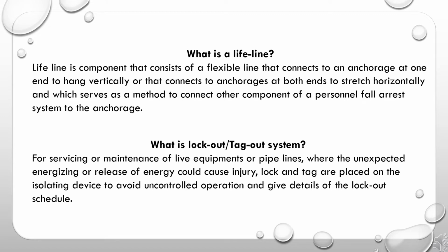What is the lockout/tagout system? For servicing or maintenance of live equipment or pipelines, where the unexpected energizing or release of energy could cause injury, lock and tag are placed on the isolating device to avoid uncontrolled operation, and give details of the lockout schedule.